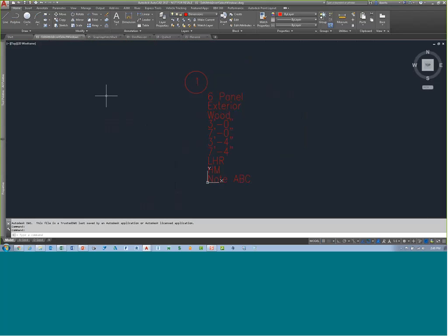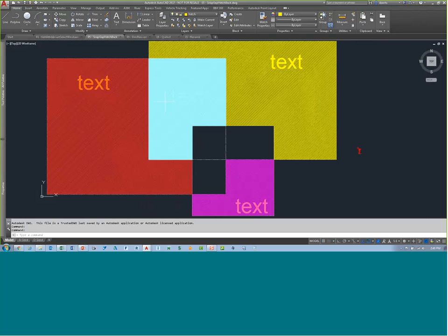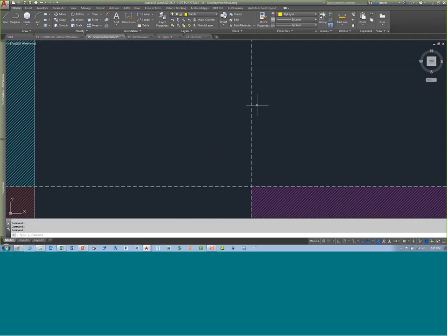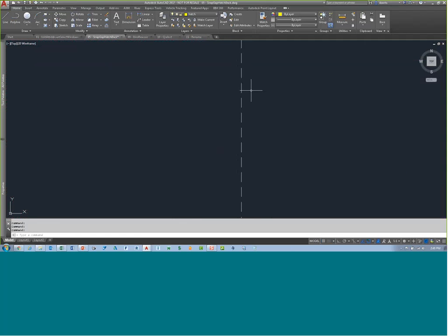So when I talk about snapping to gaps, if we zoom in here, there's a polyline here for a boundary, and it's a dashed or hidden line type. By default, if I try to select this via window crossing like this, it will pick it even though my window selection is inside that gap, if you will.